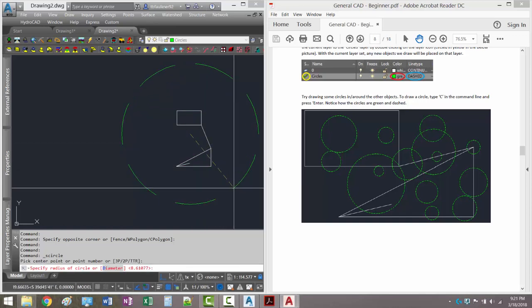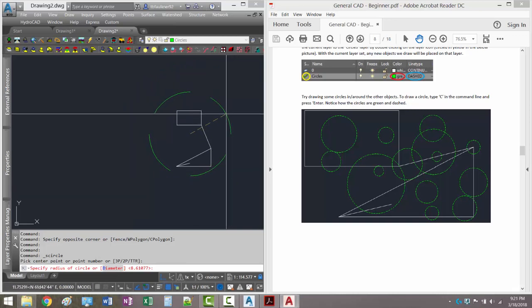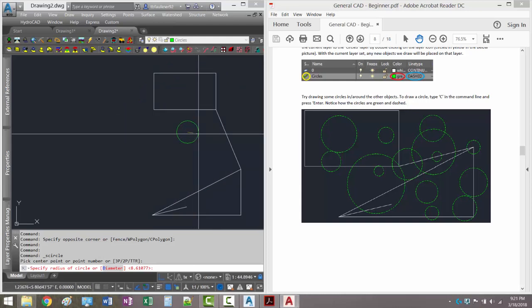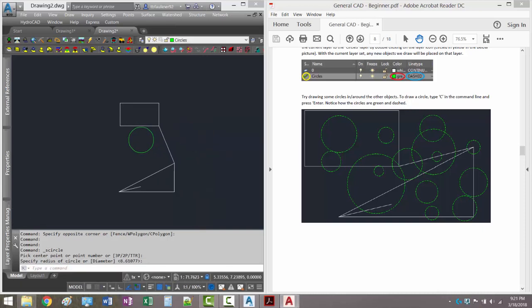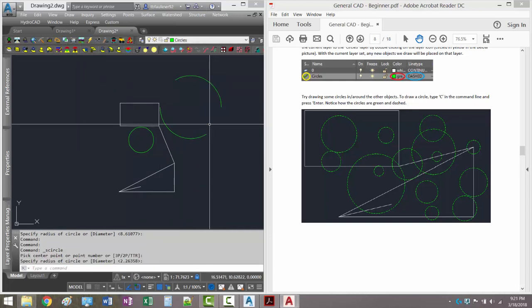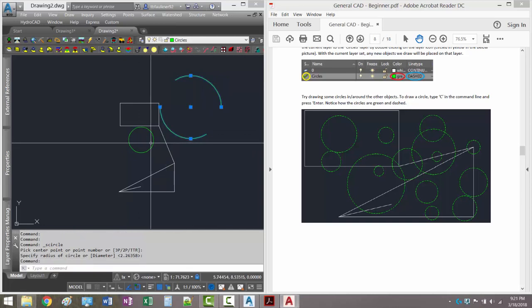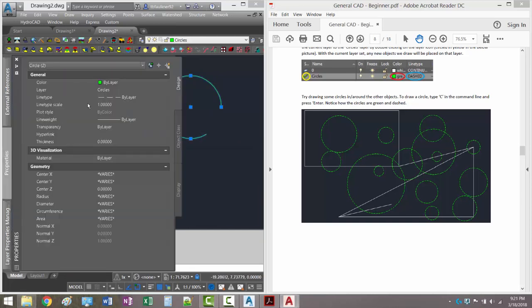And you notice here I've got that dashed line type. Yours may be appearing slightly differently based on the scale of the line. If I draw a small one, it's going to be mostly continuous here. I'm just going to draw a couple on there. Repeat that. Draw another circle. And the reason that you're seeing this is due to the line type scale. If I pick on both of these, I take a look at the properties, notice my line type scale is set to 1.